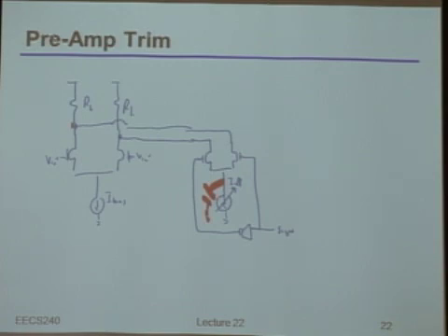So I'd argue that's another nice benefit of doing it this way: if you make the output impedance of the input devices and of that offset cancellation device high, then you don't have to load it in terms of capacitance parasitics. You don't have to screw up the symmetry. Both of those are really nice, which is why this is my default solution.